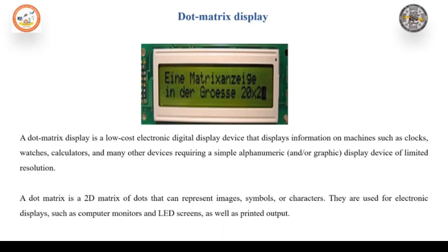The ASCII code is one of the most widely used formats, used with keyboards giving 64 alphanumeric characters, including 26 English alphabets, 10 numerals, and several other symbols. Looking at the diagram, ASCII code from the keyboard is sequentially entered and stored in 3 input storage buffers. The codes in the input buffers refer to the 3 individual characters to be displayed, so the appropriate characters can be displayed.